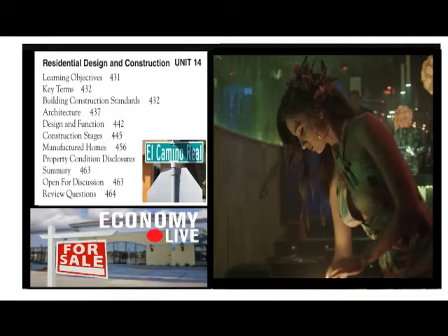Floor plan. The floor plan of a house should provide for both easy circulation and convenient access to living areas. The old railroad concept of all rooms in a line, with entry from one to the next, is highly undesirable. Each bedroom should have a separate entry, and the most luxurious plan gives each bedroom its own adjoining en-suite bathroom. As much as possible, bedrooms should be isolated from living areas.